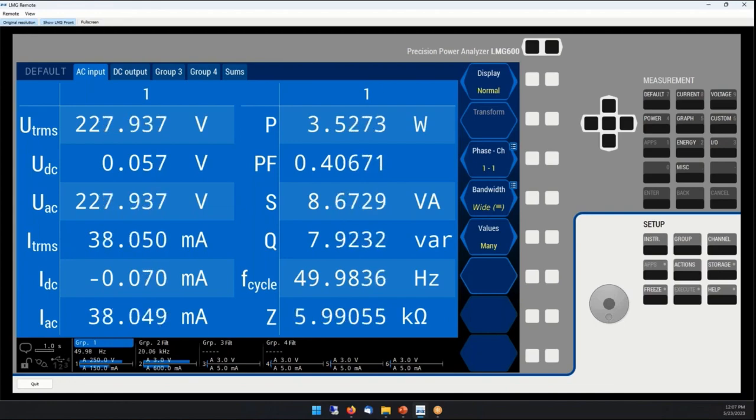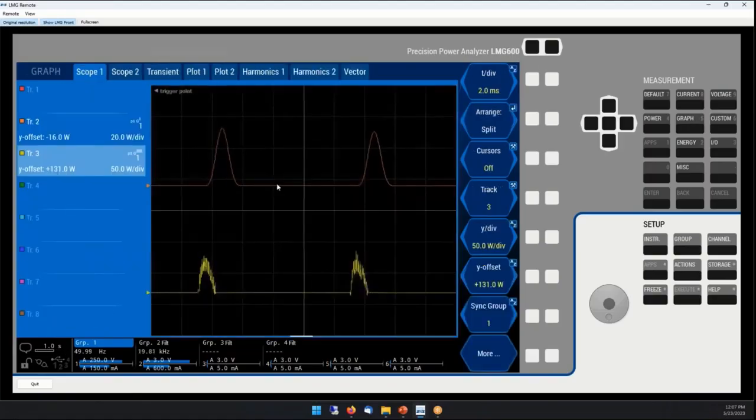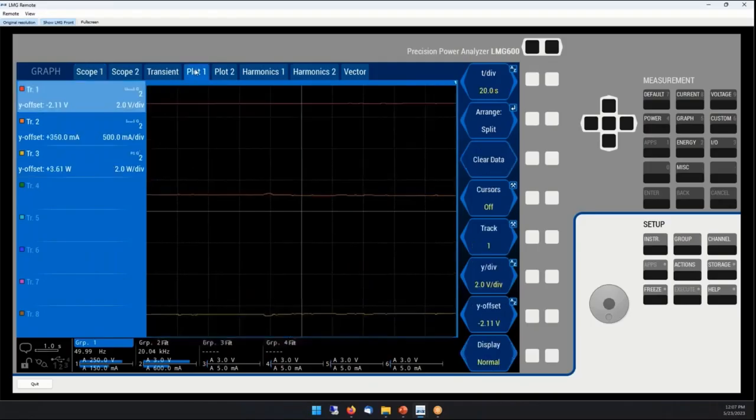So record the cycle, using the plot graph that we saw before. Record the charging process, the discharging process, the energy, the charge drawn at those stages, the power, the quality of voltage, the quality of current provided to the battery. You can do that all with the power analyzer.